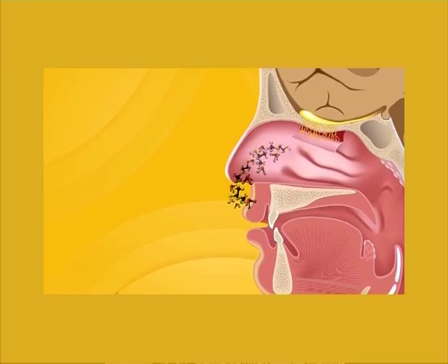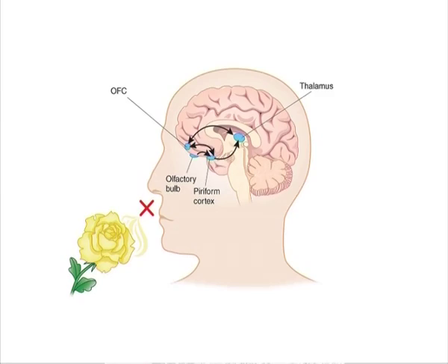The analysis with the e-nose, as a first step, needs to be trained with qualified samples so as to build a database of reference. Then, the instrument can recognize a new sample by comparing the volatile compound fingerprint to those contained in the database. The limitation is the analysis of odors made up of multiple different molecules, which is normally detected by the device as different compounds.